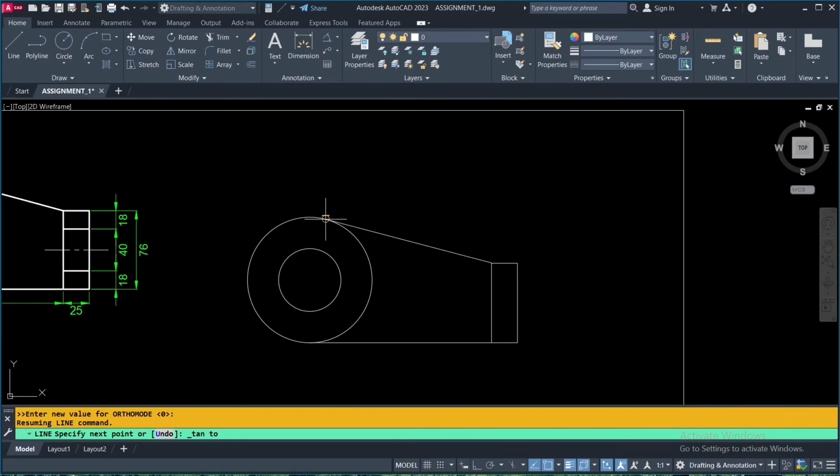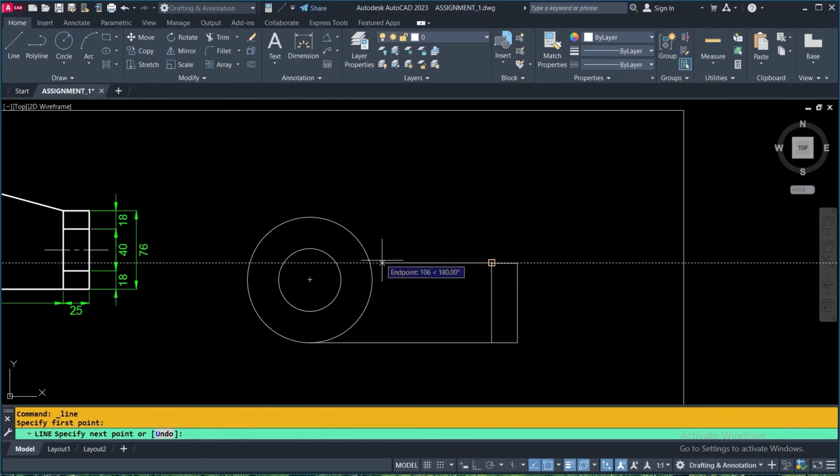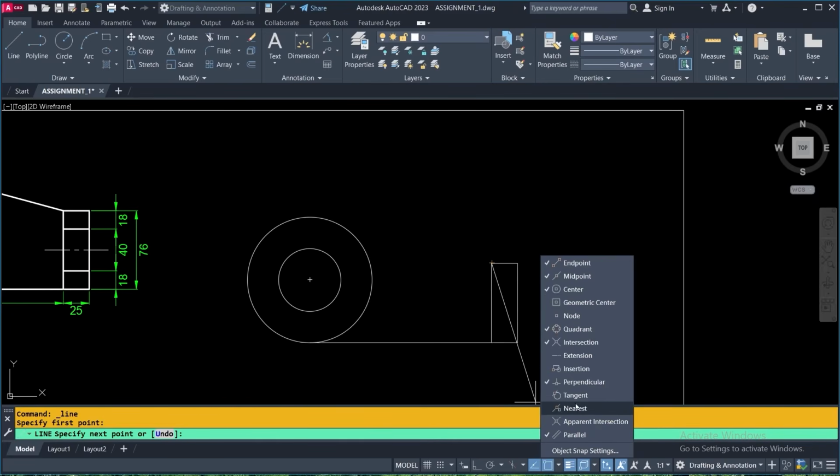This will happen for one click. Now we see other OSnap options are activated. Then pressing enter. Again I am showing, I am erasing this line, clicking on it, it is deleted. So line tool taken, starting from here, click. You see here tangent is not activated in the OSnap.